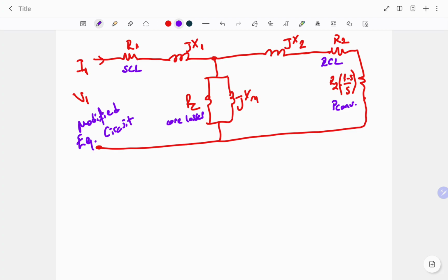So when we examine the power flow diagrams of any motor or generator, we are using the Sankey diagram representation. So we are using arrows, and the width of the arrows shows the amount of the power flowing through that point. So for the power flow diagram, we will start from the input power, and until the output power, we will subtract the losses from the system, and we will clarify the power relation between the parts.